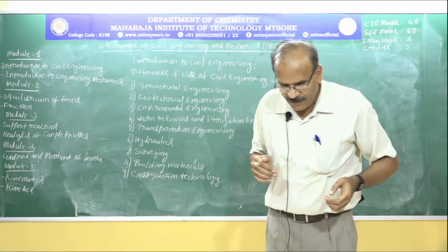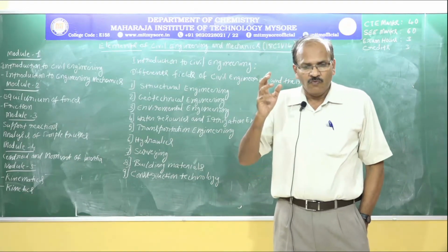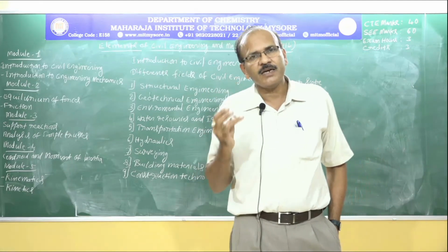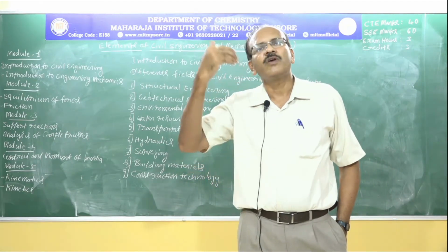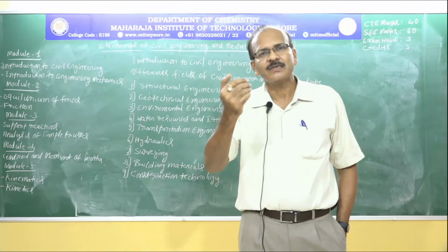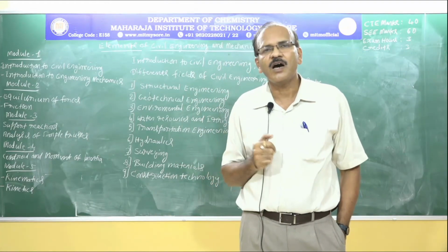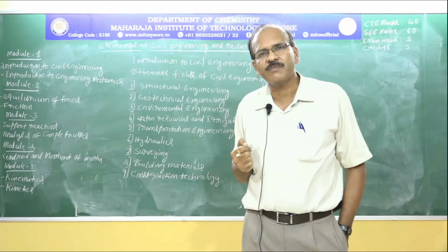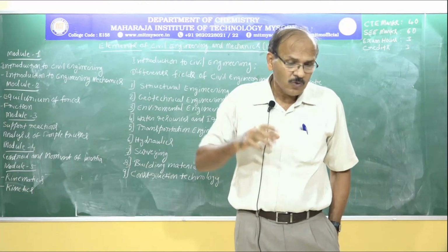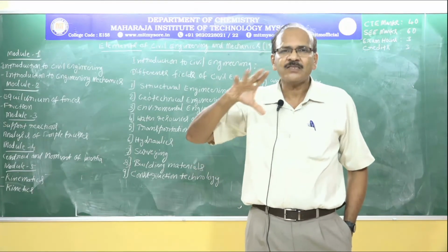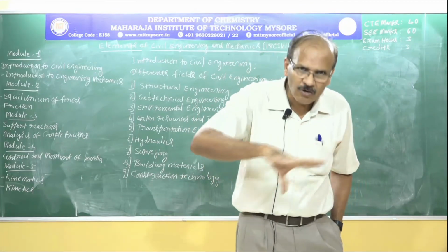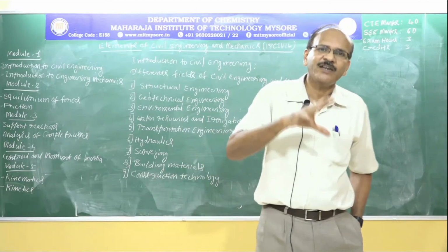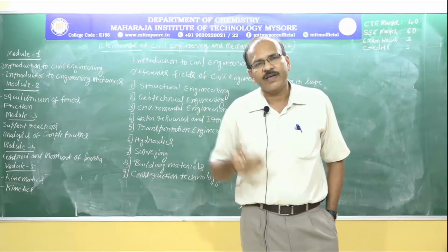For example, if I take cement, we are going to conduct the initial setting time test, the final setting time test, then find out the soundness of cement, then the crushing strength of cement, that is the compressive strength of cement, etc. The Indian Standard Code has given certain specifications on how to conduct all these tests, and also the values which the cement we are testing should satisfy.